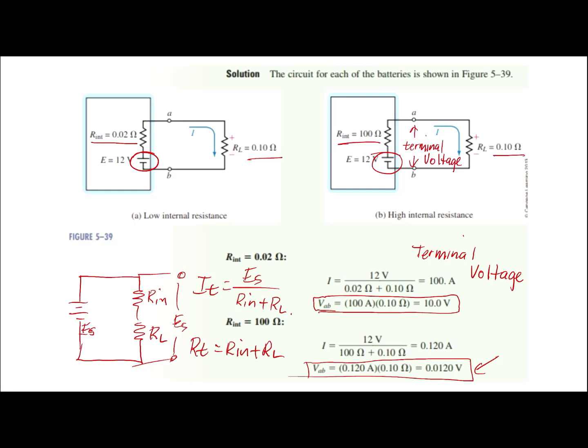That's the biggest mistake I see with beginning students, is they throw away the concepts of a series circuit and the fact that current is the same throughout. Kirchhoff's voltage law applies. So the sum of the voltage rises equals the sum of the voltage drops, and so on. So I think if you just remember that, you'll do a lot better on these type of questions.